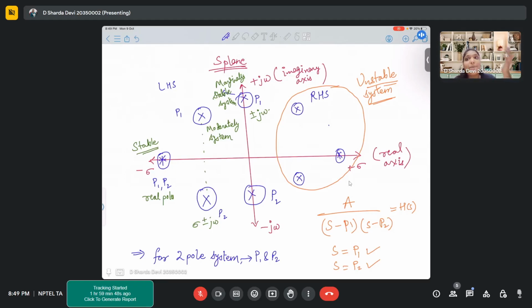So that's why we consider it. But now, let's say it is fabricated such that that particular phase, rather than being left as a PN junction, is terminated with an insulator or something. So at that point, there is no junction present for that end phase. If there is no junction, then there is no capacitor or capacitance. So that is the idea.